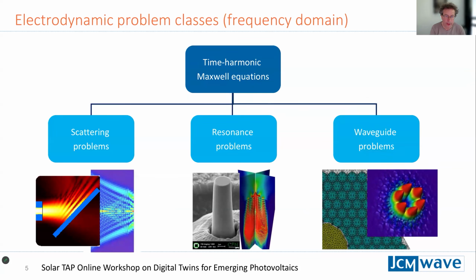However, typically we concentrate on Maxwell's equations. There we work in the frequency domain. It's usually solved with time harmonic Maxwell's equations where we concentrate on one specific wavelength. And then for a wavelength scan, we have to do various simulations at the different frequencies.